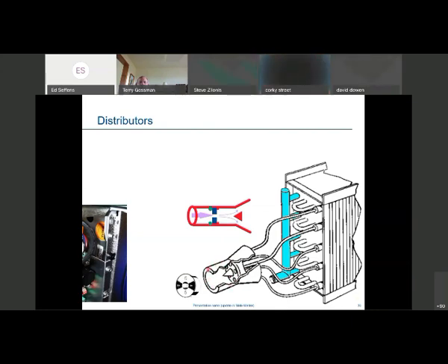And you look at the different models that they may have, maybe like a 11, 28 or 25 or so. This nozzle actually fits into the orifice right here, or the inlet portion of that distributor. And then the 5 here, that does not necessarily correspond with capacity. That's just the size of the orifice itself, right?